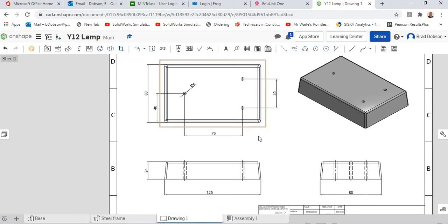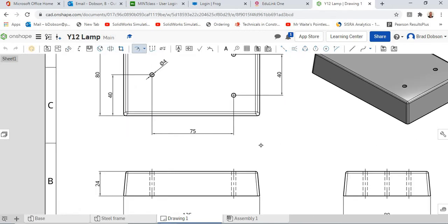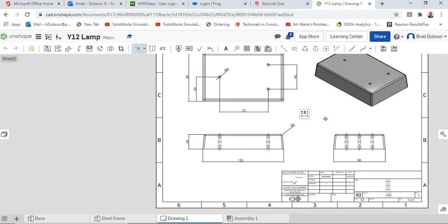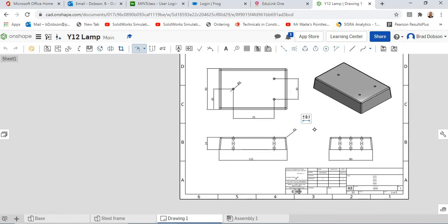Possibly the only thing that we need to look at is putting the fillets on there. So hopefully, if I zoom in, the idea of that it's got these radiuses on the top corners, that type of thing. Again, you don't really need to go around dimensioning every single one. Again, an assumption would be if you dimension that corner radius, that all the radiuses are going to be 2mm. Again, you could always write that as a note on the drawing as well. Save you having lots and lots of messy dimensions on there.